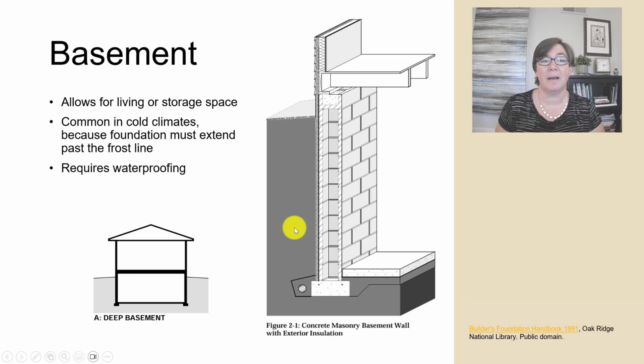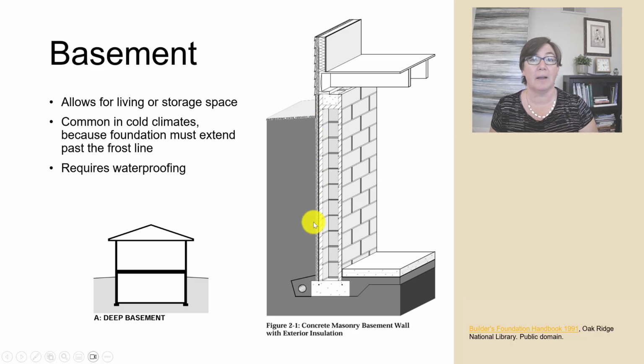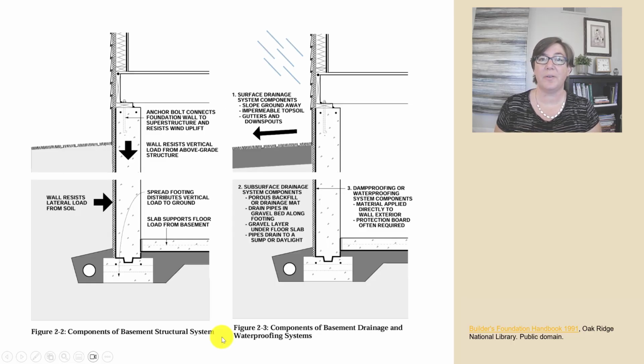An important point of basement foundations is that they require waterproofing in order to create that livable space inside. Here we've got two diagrams of the same system. Starting on the left, let's talk about the structural system of this foundation type. So we've got the house above here, and all of the weight of that house is coming down to rest on this foundation wall. All right, that load comes down and rests on this spread footing, right, which in turn rests on the soil.